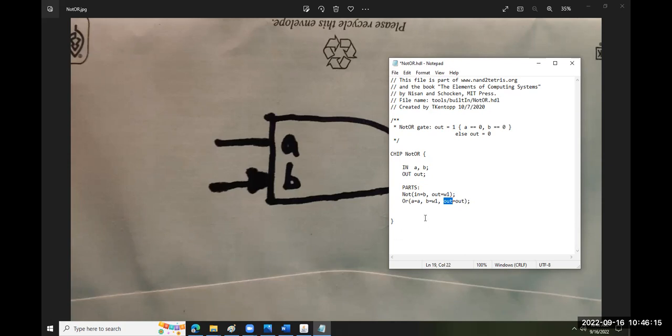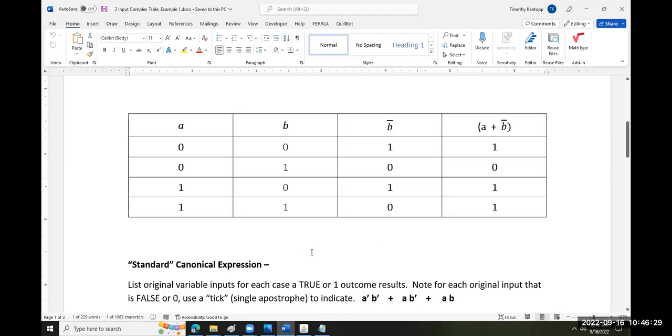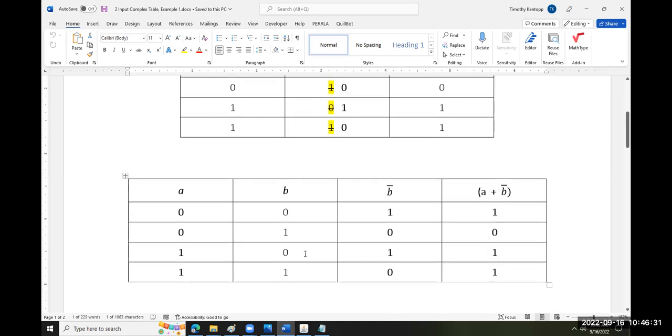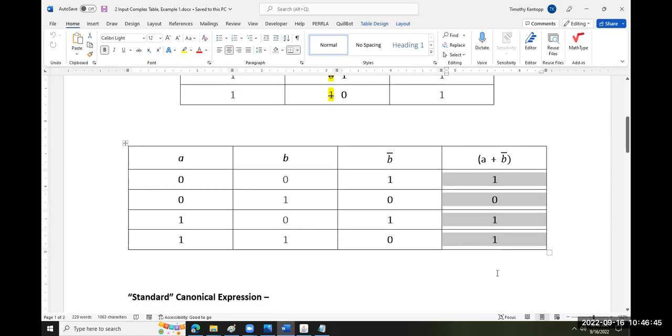Yes. Okay. So what I'm going to do is save this, load it, and see if my values match what's in my truth table. I've got to check this out. In terms of the software version of this, I already know what I'm supposed to get, right? If I put in a 0 and a 0, I should get a 1. If I put a 0, but the B is 1, I should get a 0. Everything else should be 1, which is kind of weird, but hey, by intention, by design.